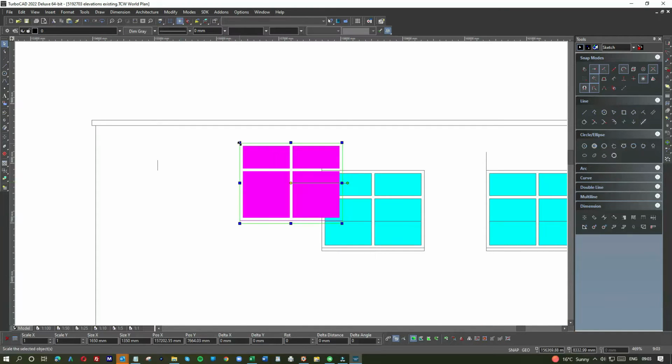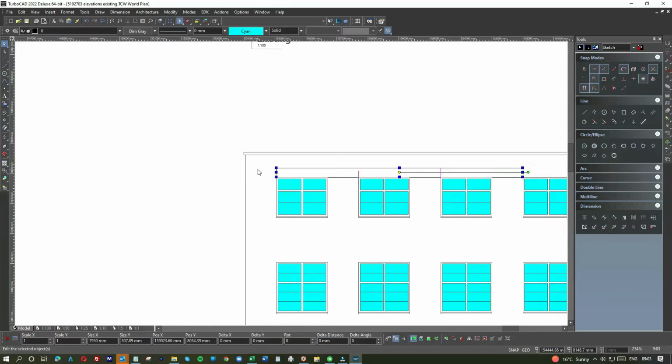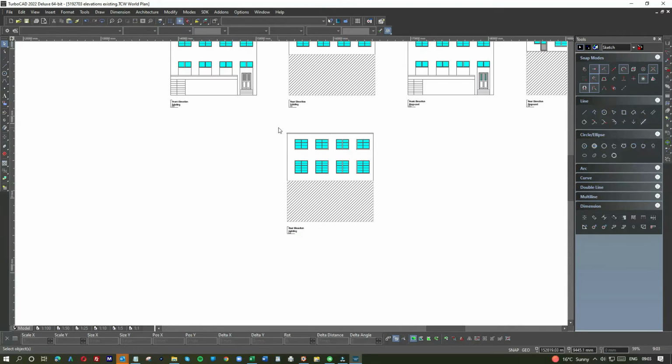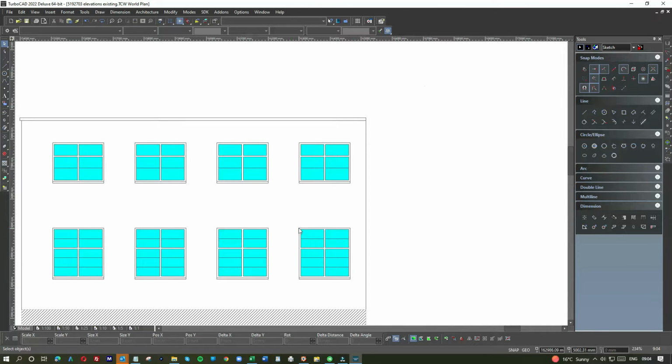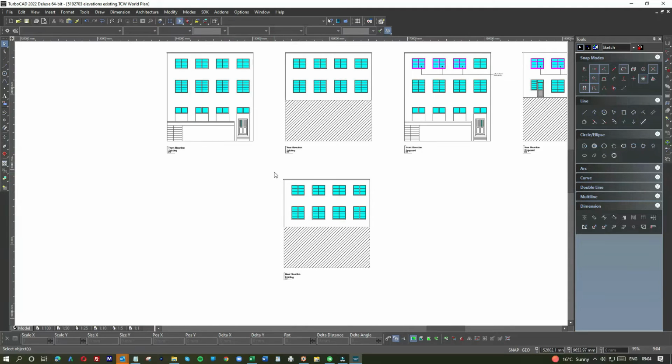And as I say, once you get the location, the height, and the vertical and horizontal location, it's easy to repeat. Now these windows were slightly taller, so again all we did was take the frame and the size of the building from the front elevation, make a copy and flip it over, get rid of everything on the ground floor, position the windows above, and then create these two windows. Once we create these two, copy paste, copy paste, copy paste, and this took about 30 minutes to create the rear elevation for this particular project.